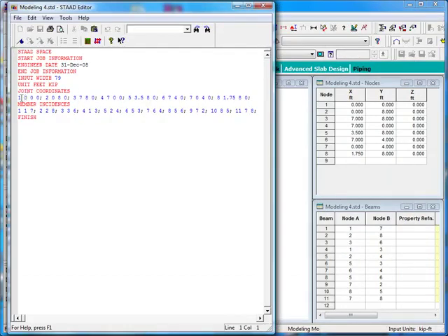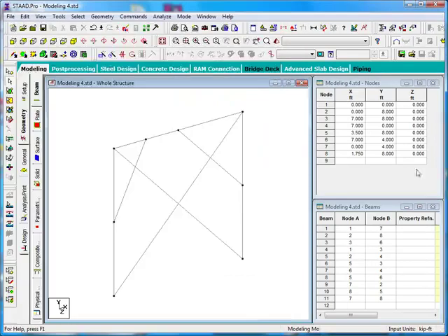Don't ever concurrently make some changes in your Staad editor and then some other changes in the graphical user interface tables, because that will cause some confusion, and Staad will have a hard time reconciling which changes are to take precedence. Some of that work will get lost in one location or in another. So always work in just one location and then save and close at a time.